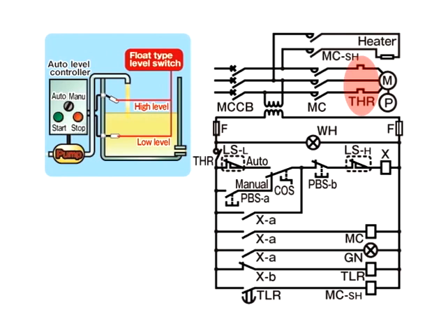As excess current passes to the motor, heat is generated in the thermal relay THR heater. The THR relay of the sequence circuit opens because of heat generation in the THR heater. Current is cut off as the THR relay opens and the X coil demagnetizes. Then XA turns off, demagnetizing the MC coil and turning the MC off.